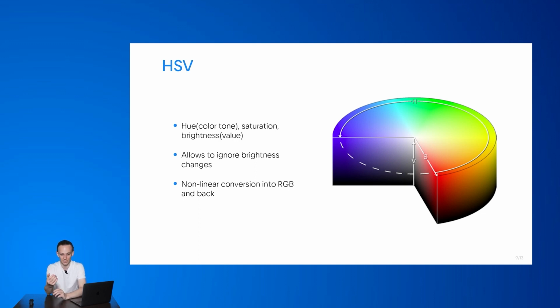The problem is that in certain areas, for example, in very dark areas, it tends to increase the noise values. If we're filming some dark area, a dark room, we get the original image from the camera in RGB color space, and in HSV color space all those noises are enlarged. So two neighboring pixels of the dark image, let's say one of them is slightly redder than the other and the other is slightly greenish, could be very distant from each other in terms of the color tone, the hue.